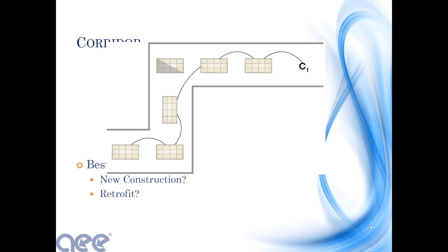You still have to run control wire. I work for Lutron and I sell digital drivers, so yes, digital is the best way to go. But your install cost is the same, so for this one, why not just go with 0 to 10 volt, right? Now you've got one zone, controlled the same. You can use that technology to have all the fixtures at 10%, 50%, 75%. And so that's why I say there isn't a one size fits all.